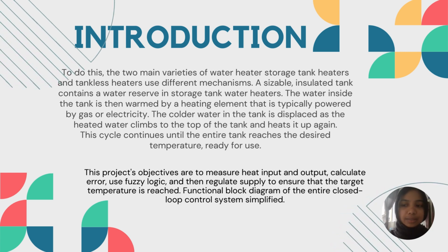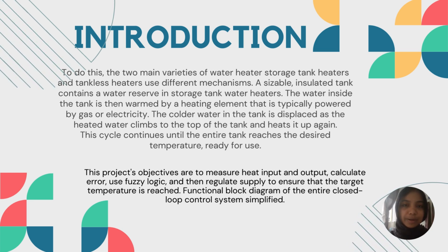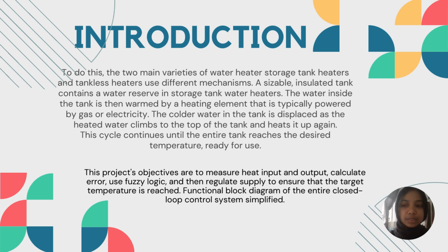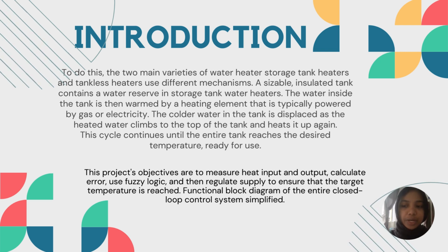The water inside the tank is warmed by a heating element that is typically powered by gas or electricity. The colder water in the tank is displaced as the heated water climbs to the top of the tank and heats it up again. This cycle continues until the entire tank reaches the desired temperature, then it is ready for use.